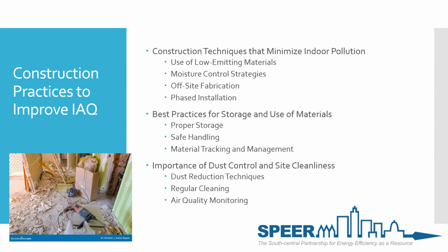And then regular cleaning, so implementing daily cleaning protocols to reduce accumulation. I know a lot of times with pre-drywalls, there's a lot of builders that have a policy where you always have to have it broomed out or blown out daily to keep contaminants low. That's a great way to do it. There's others that just don't have that as their priority. So there's a ton of contamination. There's a ton of products that get trapped inside the walls and/or behind bathtubs or trapped in the seat of the shower. That stuff just will off gas over time.